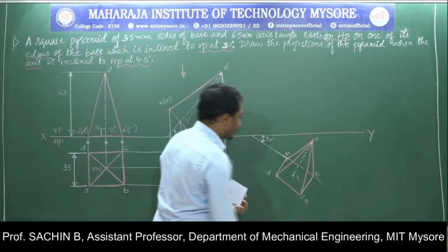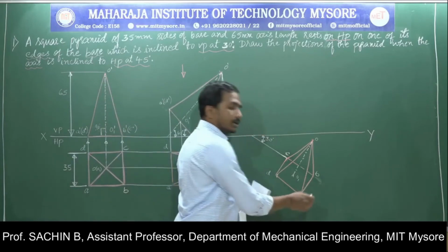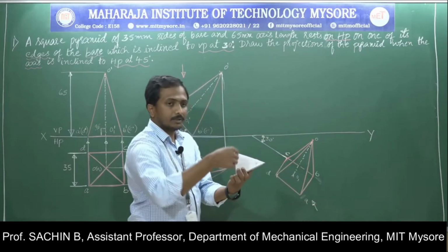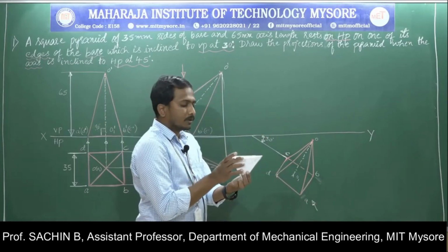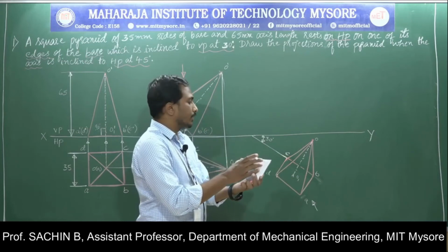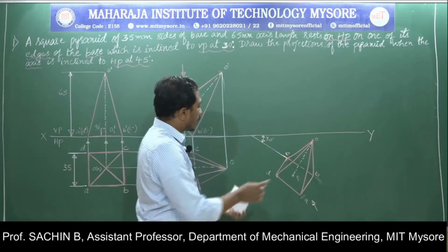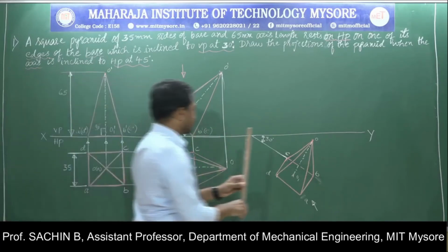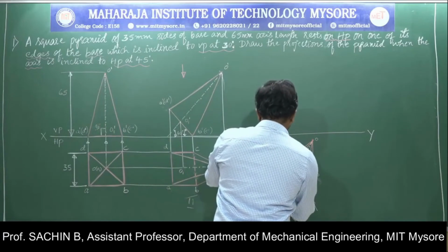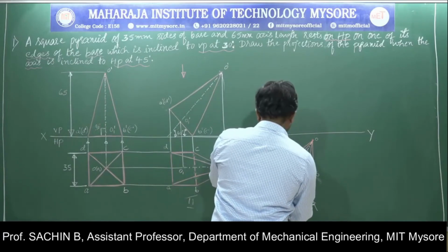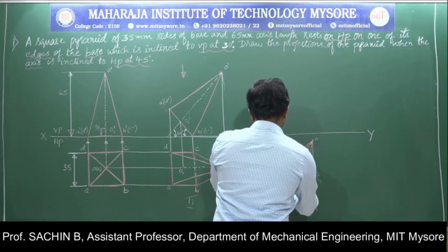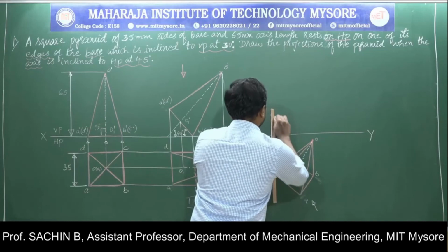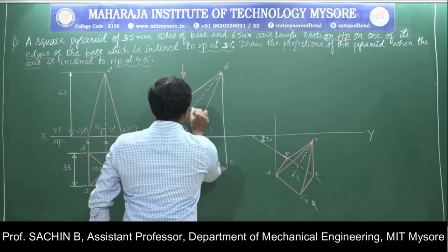While drawing the front view of the object, the observer is clearly present over here. From the observer, we are drawing the front view of the object. First, I will go for projecting the lines that are necessarily required for me to draw the front view. First, I will go for the D point. I'm starting here. Again I am drawing the projection line from here.